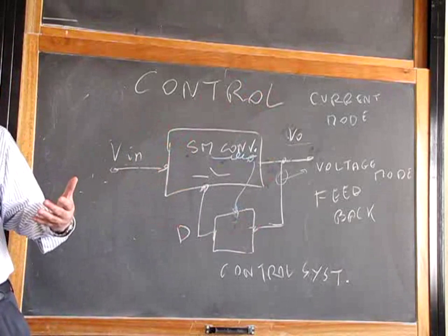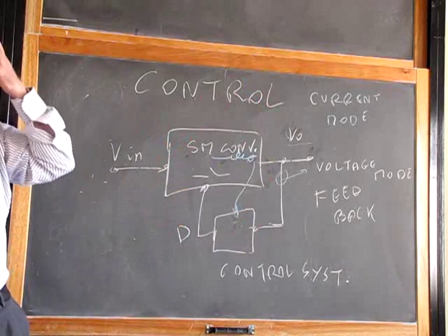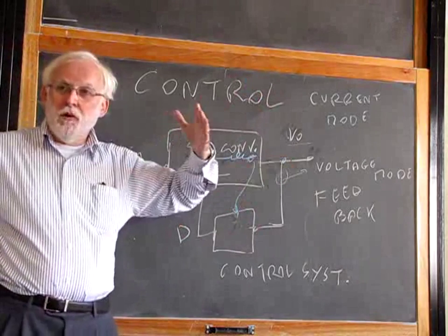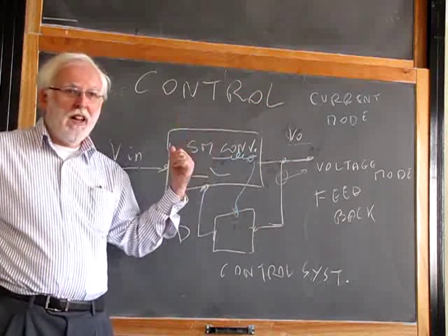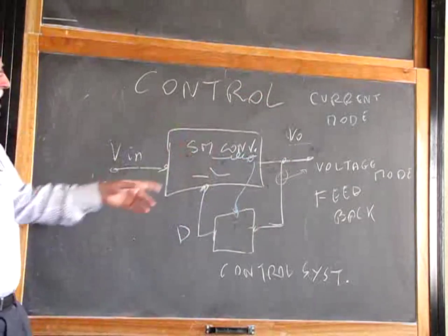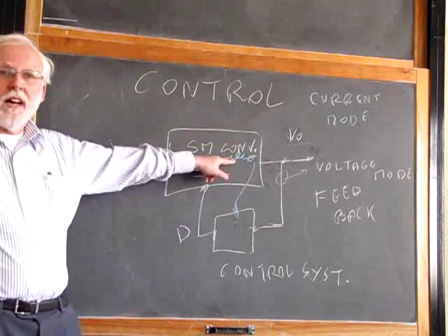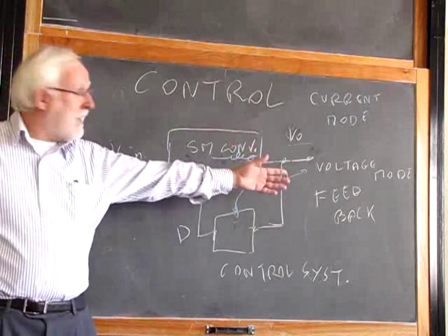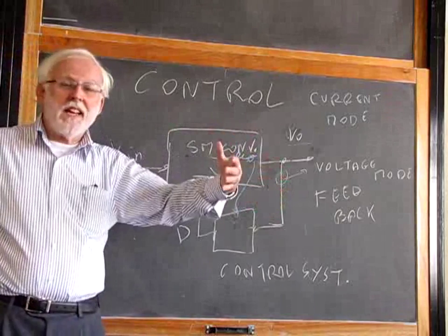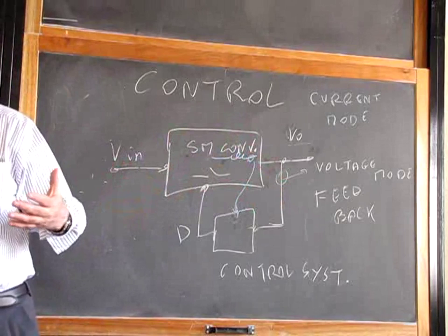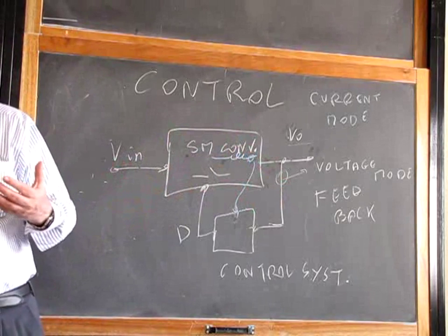That is a standard feedback system. But if you wait until the output voltage moves to take action, you are late because all your state variables have been screwed up. Your inductor current has changed, the capacitor voltage starts to change, at that point you say, oh, something is happening, let me correct. Too late, could be, for some control systems.